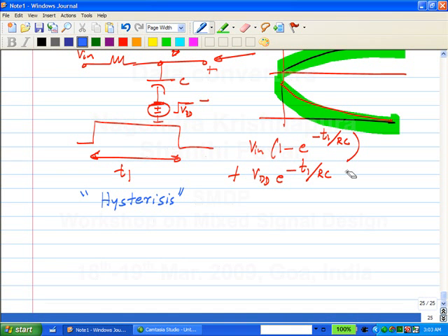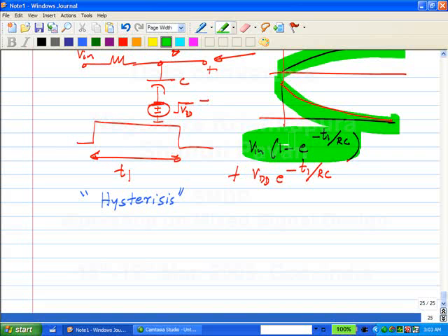Here you see that the difference is reduced in magnitude because of memory, because the capacitors are not charged to the full V in. And they have not forgotten the old decision. So the inputs that are most likely to get affected are those where the input is near 0. If this part is small, then it's very easy to get corrupted by this large VDD.